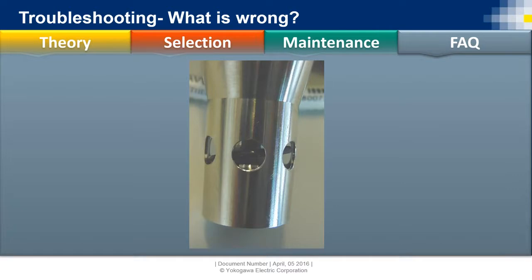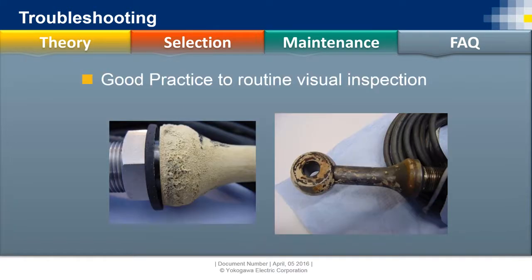And then this is one that I have come across in the past couple weeks. Customer couldn't figure out why the sensor wasn't working, and they sent me a photo of it. I don't know if you see it there, but there are internal O-rings in these sensors, and they have certain pressure ratings. So if we exceed those pressure ratings, or even if there's chemical attack on the internal O-ring, that's going to cause you measurement errors. In this particular case, the electronic side of the sensor wasn't sealed, so process was getting inside there and shorted the sensor.